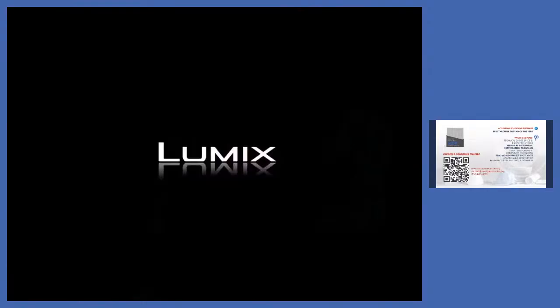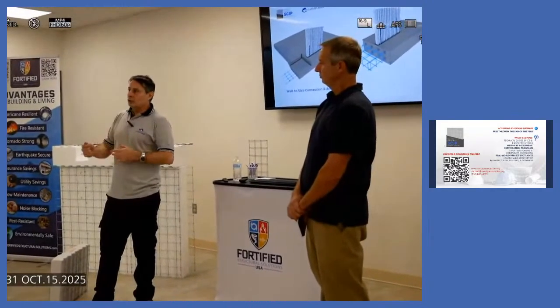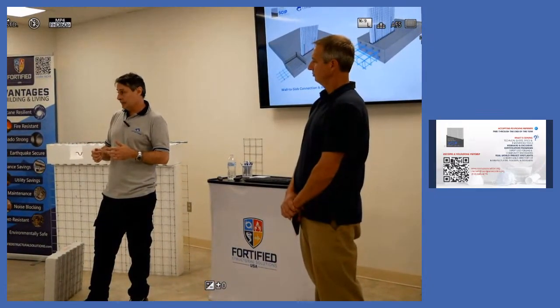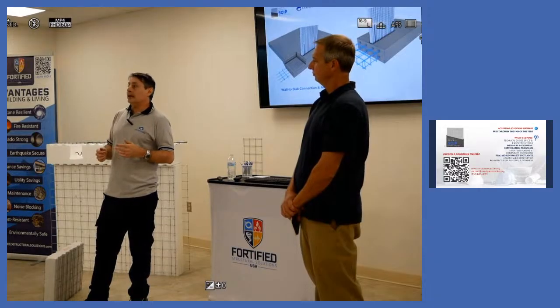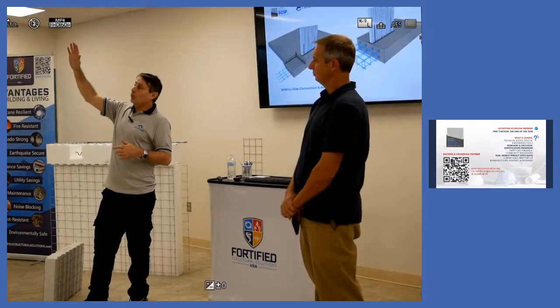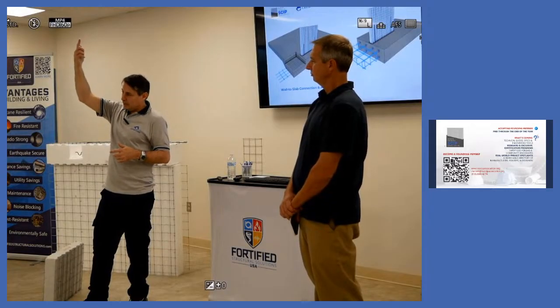But remember on your model, I offered you to make one wall working as an inverted beam. So in that case, you don't have anything. The thing of working as an inverted beam is that it changes the building procedure. Remember that I told you that you can take away all the shoring until that wall that is on the upper level is already working.